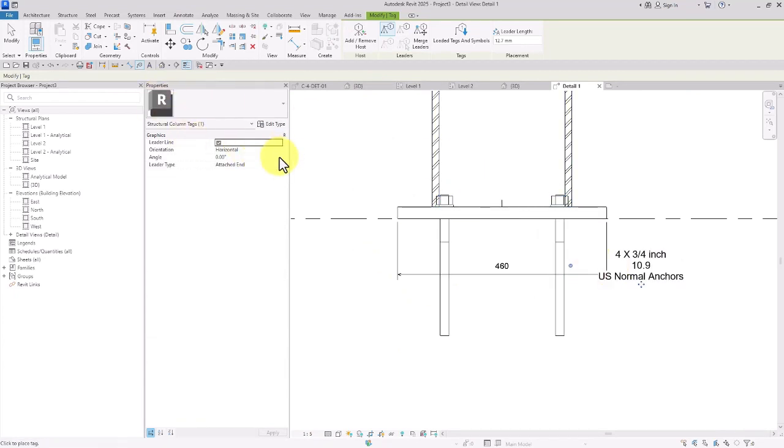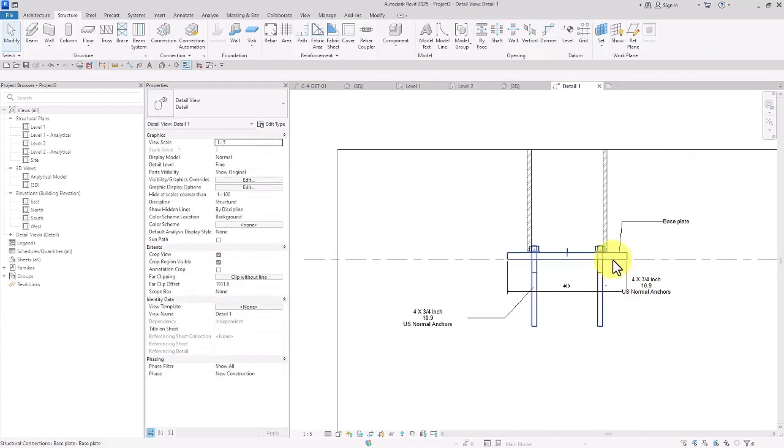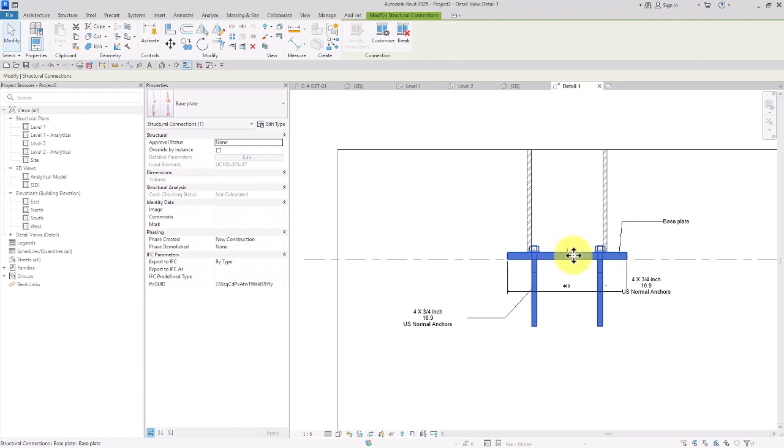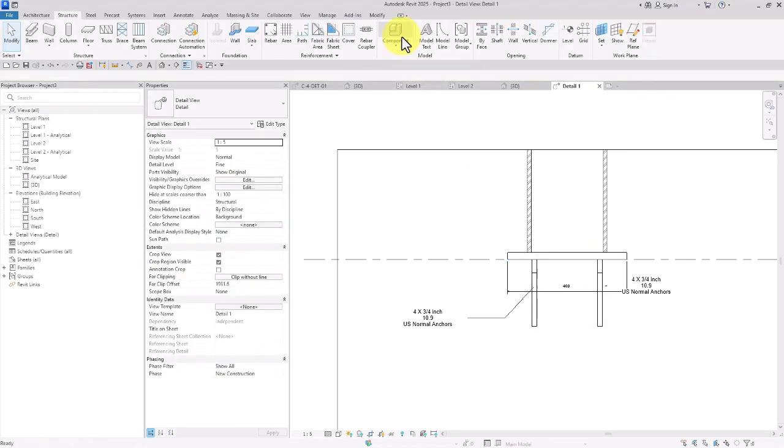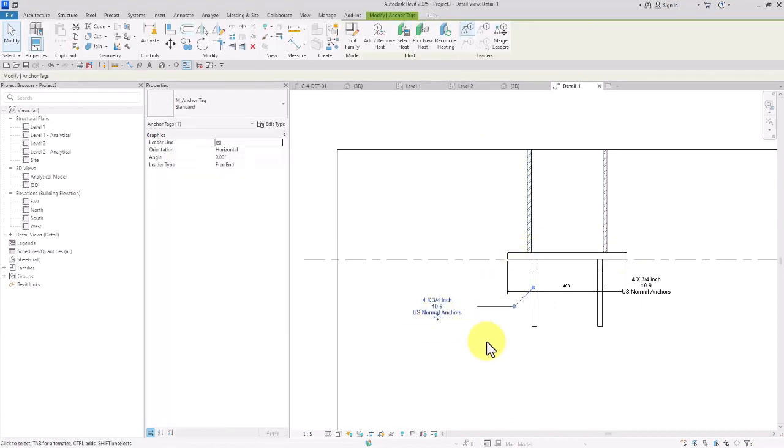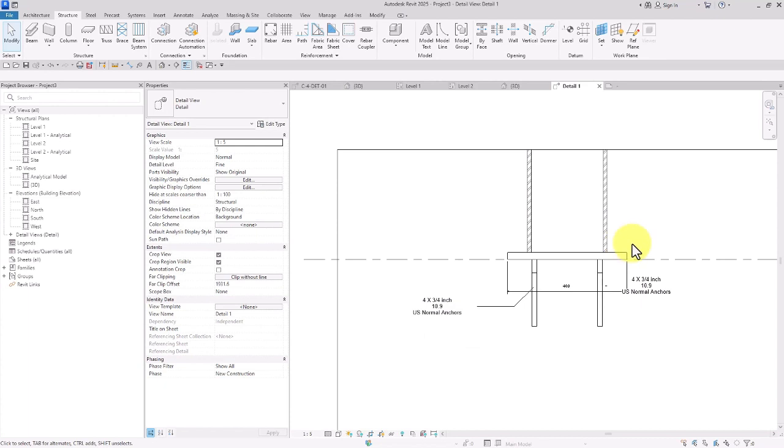Here, I'm going to set this on free so that I would be able to move them around easily. Just like this. See? In Revit 2025, if you select the connection and then up here, click on break, and then if there was any tag set on them, it'll retain them. It's not going to remove anything. And if an element or a tag was removed, it means that the tag is not set on the connection. But in previous versions, it would have removed everything completely.